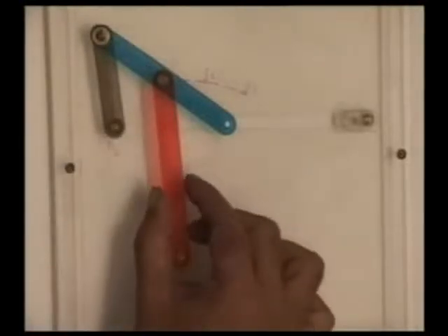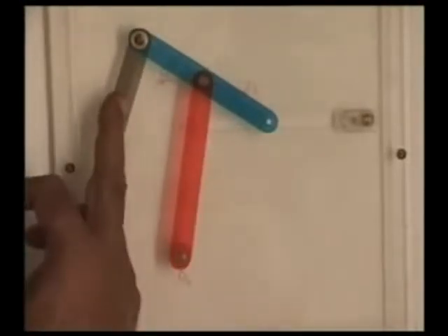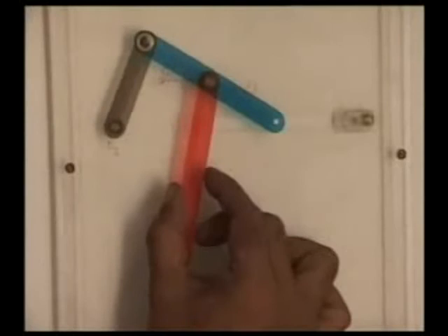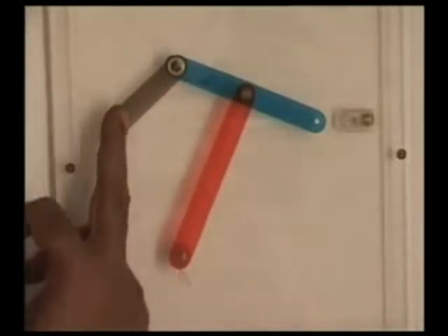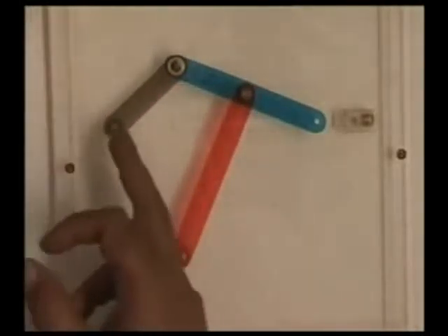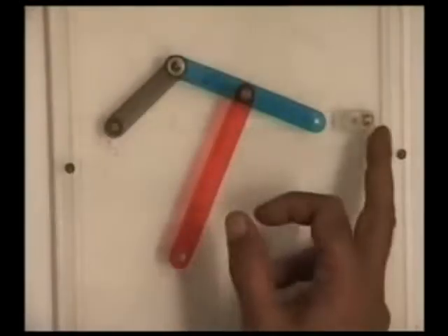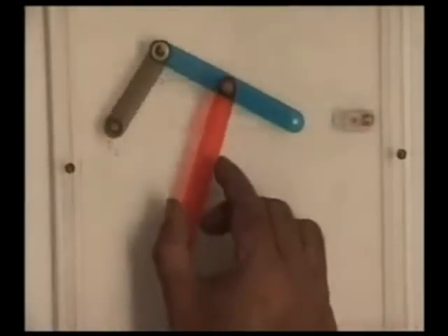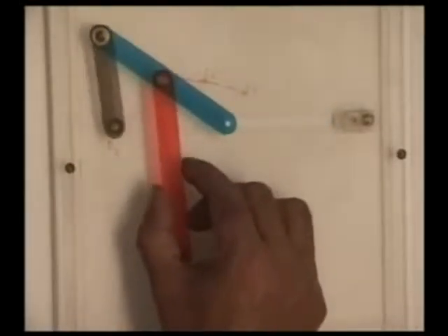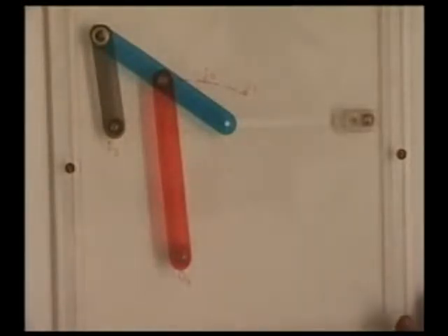As it goes from position 1 to position 2, this rotates by a specified amount. As it goes from position 2 to position 3, again it rotates by the specified amount which was dictated by the original slider crank. So this is what we call a two-stage synthesis. So all the methods that have been taught so far can be cleverly used to design more complicated mechanisms, rather mechanisms with more complicated motion requirements.